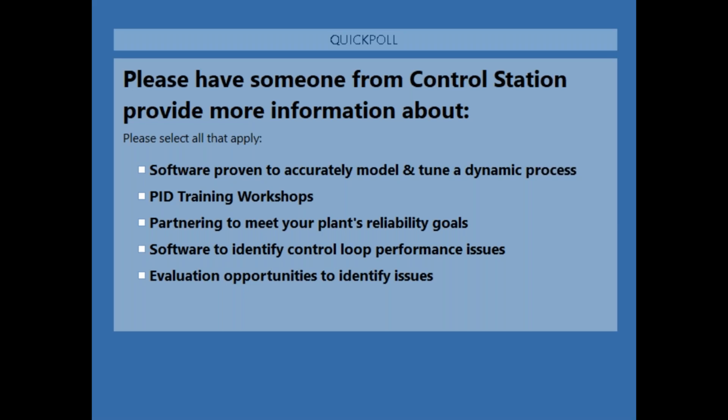Whatever vendor A says as far as integral may differ from vendor B. Vendor B might be repeat time in minutes, and vendor A might be repeats per minute.